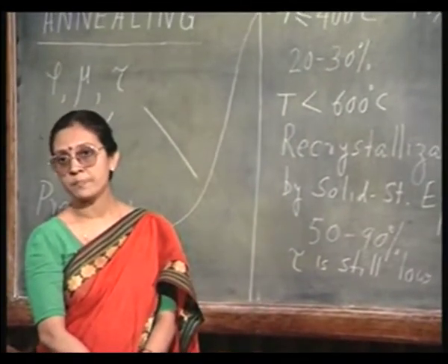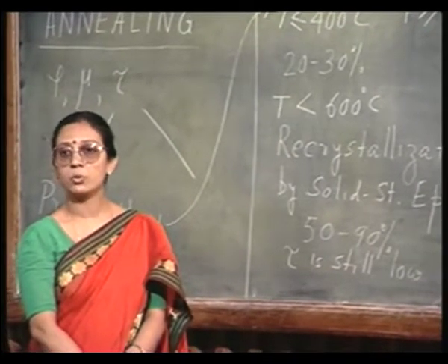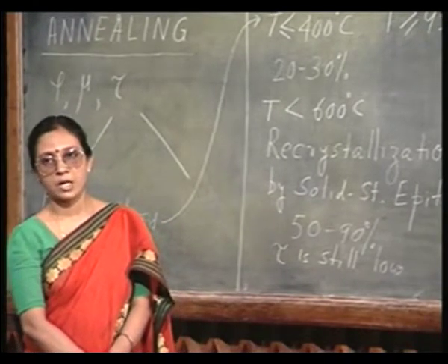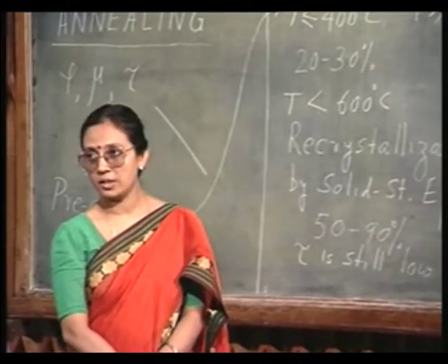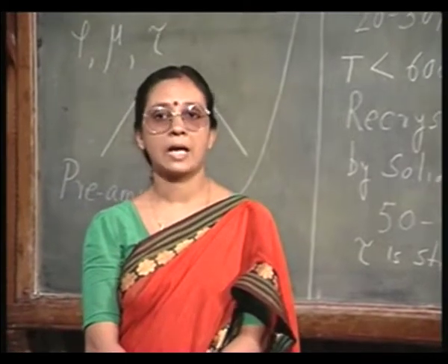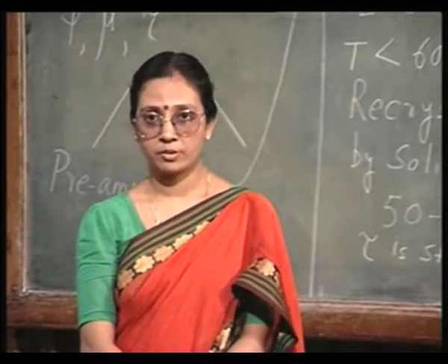On the other hand, if you are really very particular about lifetime recovery, you have no other option but to go to high temperature. So, this is about the pre-amorphized material, in which case by 600 degree centigrade you have considerable carrier activation.